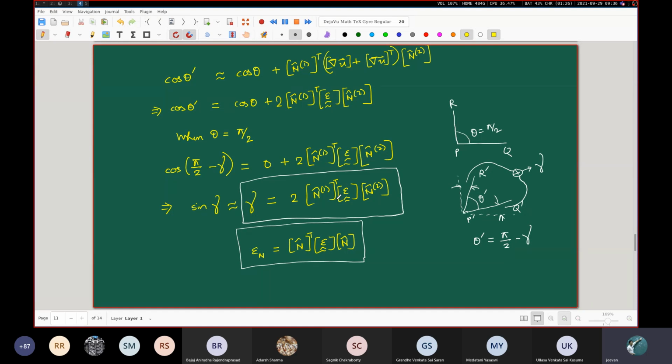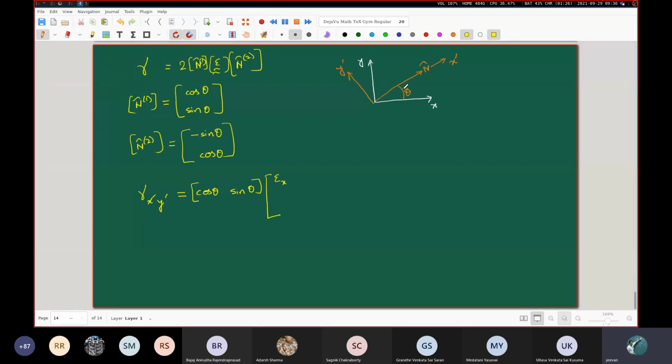So we are trying to obtain the shearing strain associated with these two mutually perpendicular lines. So this formula pertains to this situation where you have two mutually perpendicular lines. Now, when we are doing this problem, you see this one direction we have taken along x dash. In order to use that formula, we must take another direction which is perpendicular to it. The one perpendicular to it is this y dash. So this angle here is 90 degrees. Since x dash referred to the original x direction is theta, this one should be theta plus 90 degrees.